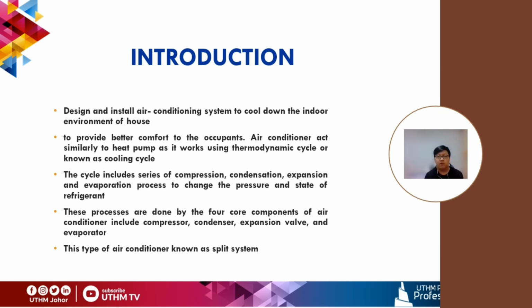Air conditioning itself acts similarly to a heat pump, as it works using thermodynamic cycle or known as a cooling cycle, and it is simply a closed circuit system that circulates refrigerant to a different point to conduct different heat transfer to promote cooling. The cycle includes a series of compression, condensation, expansion, and evaporation process to change the pressure and state of refrigerant to absorb and release heat.